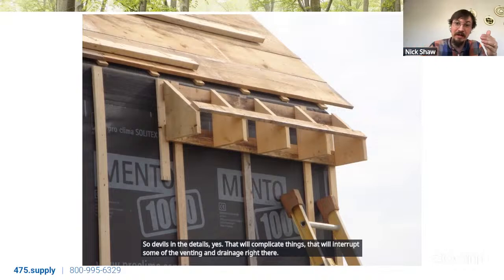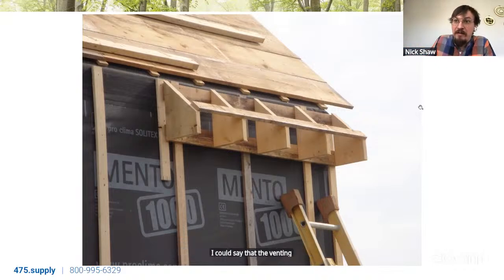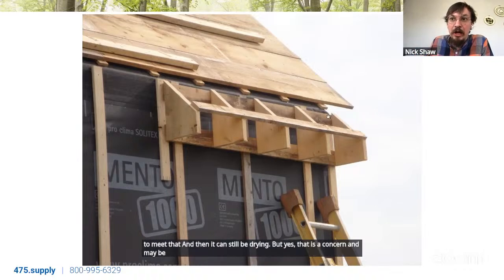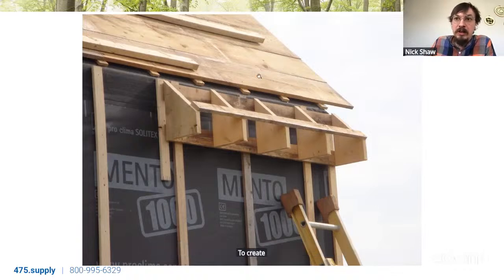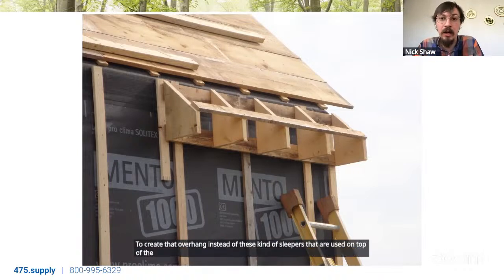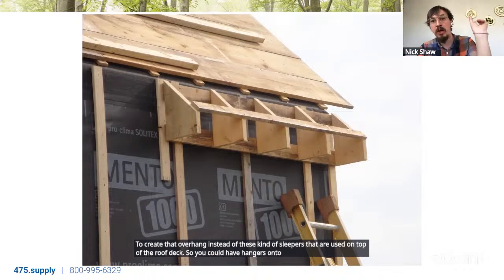I could say that the venting is now happening from that outside in a little bit to meet that, and then it can still be drying. But yes, that is a concern and maybe a reason to use hangers applied to the wall to create that overhang instead of these kind of sleepers that are used on top of the roof deck. So you could have hangers onto that wall that are just brought up to the proper height.